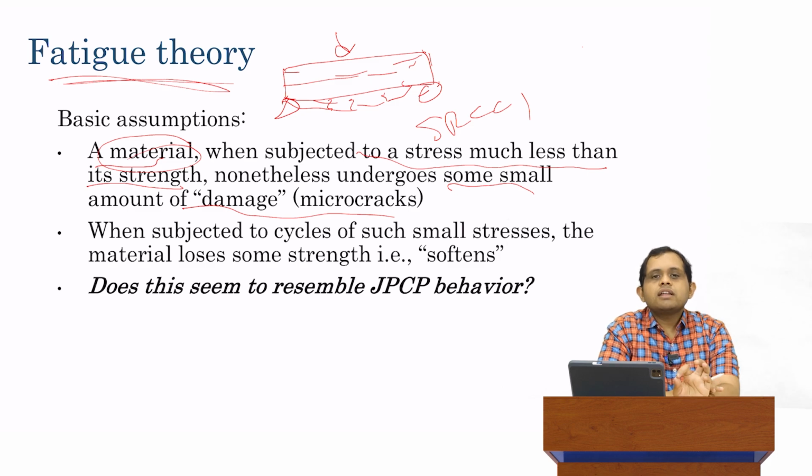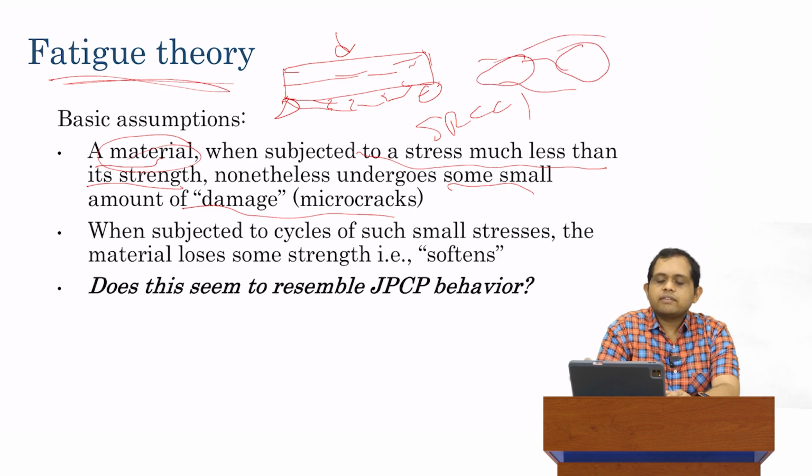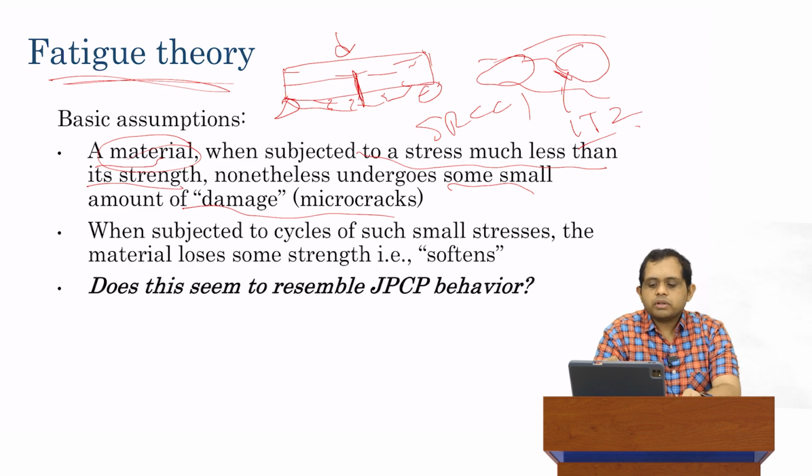the elastic range, some tiny amount of cracking occurs. For example, if we have concrete, we might have some aggregates. In between the aggregates, we have the paste, or the mortar, and it's possible that the cracking might happen here in a tiny segment, which is generally called the ITZ, interfacial transition zone. A small amount of micro cracking could develop over there. It's so small that it's not a macro crack. You cannot see a proper crack developing, but nonetheless, due to this small amount of load, a small amount of stress, these micro cracks do develop.